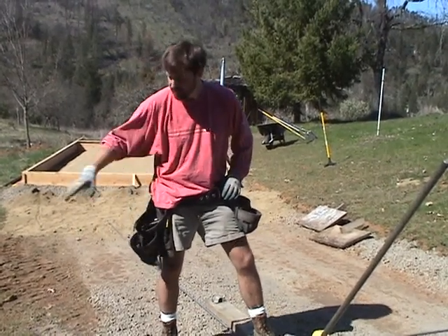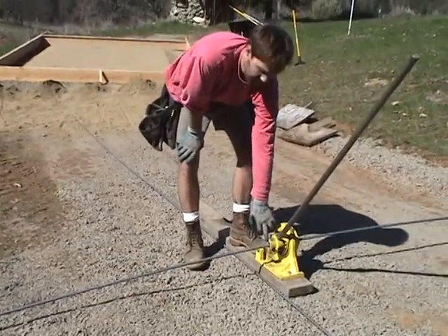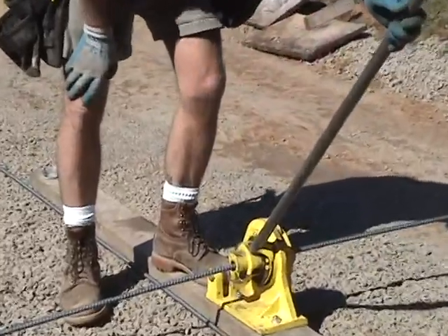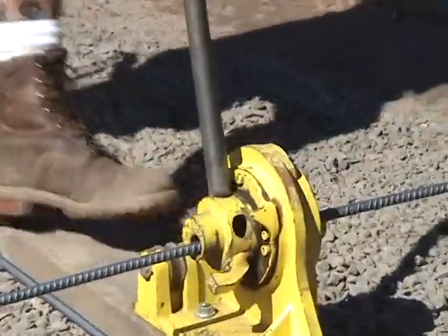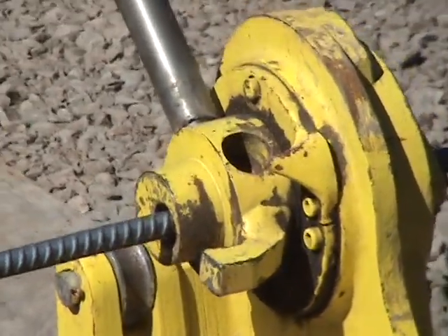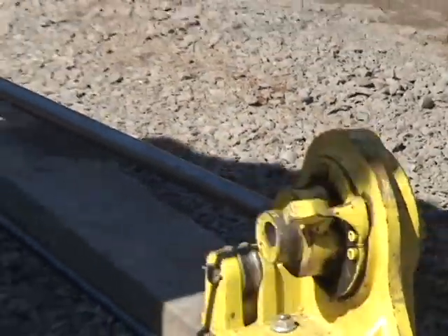measurement. So now I've placed the rebar inside the center loop here of the rebar cutter. The cutting apparatus is right about in the middle here. It's the same mechanics as bending it, it just is a different hole. As we pull it back down, it takes a little muscle, it's going to snap it off. And there you are, cut to length.